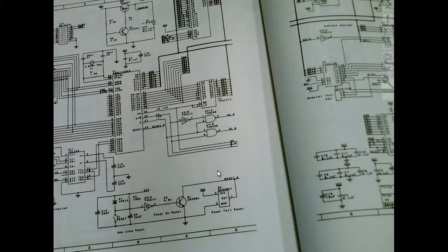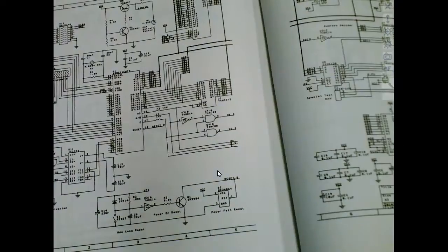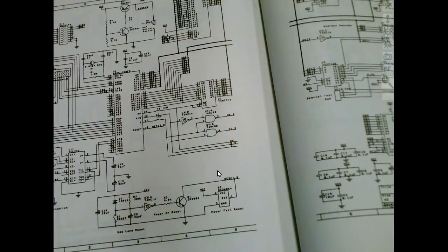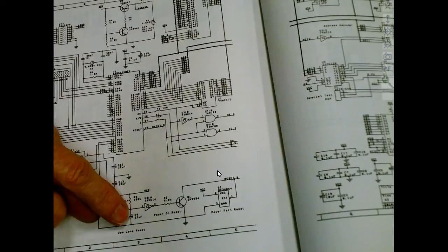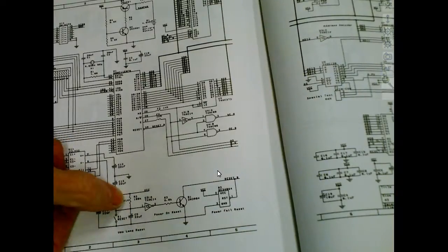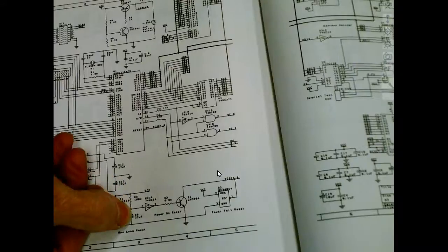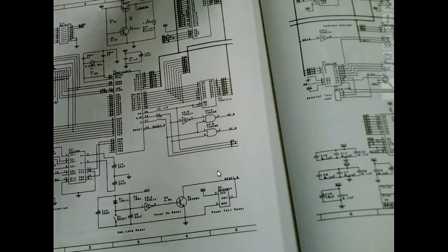So if you ever get one of these that locks up, and it locks up just like these computers do, and they don't have resets on them, what you do is you unplug them and pull the battery out. And then when you plug it in, it does an automatic reset with this little circuit right here. This little circuit is a capacitor. It charges. So when it sees the power supply come on, the capacitor starts charging. When it gets up to the threshold of the Schmitt trigger, it automatically generates a reset for the computer. So this is what resets the computer when you turn it on.